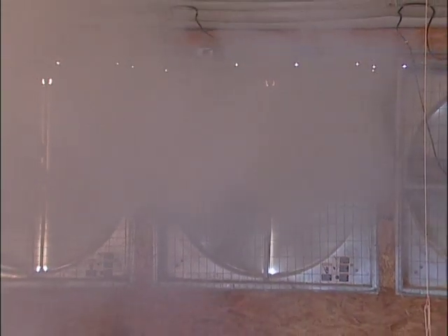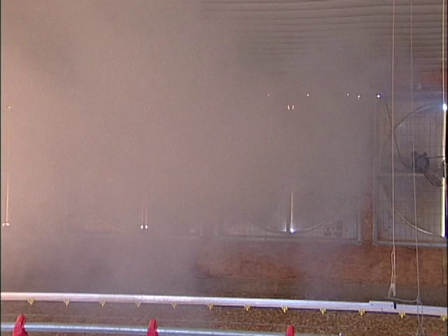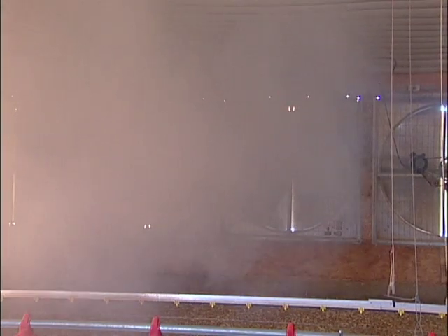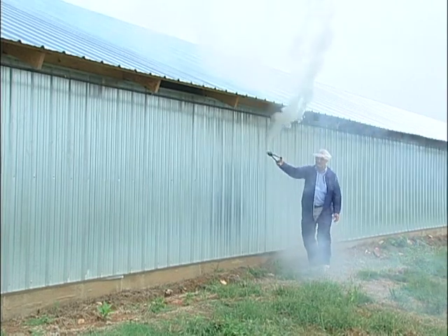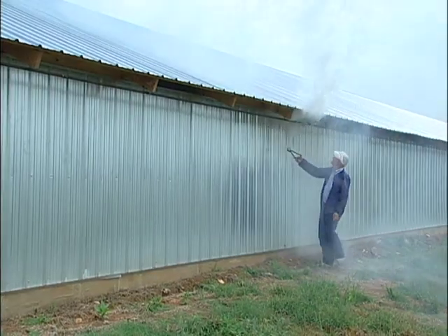Now what's real critical is in the wintertime, you've got to cover up your summer fans because it makes it too difficult to get the pressure right. So you can see it leaks all the way around and up and down around that baffle, even though it's got a rubber seal.